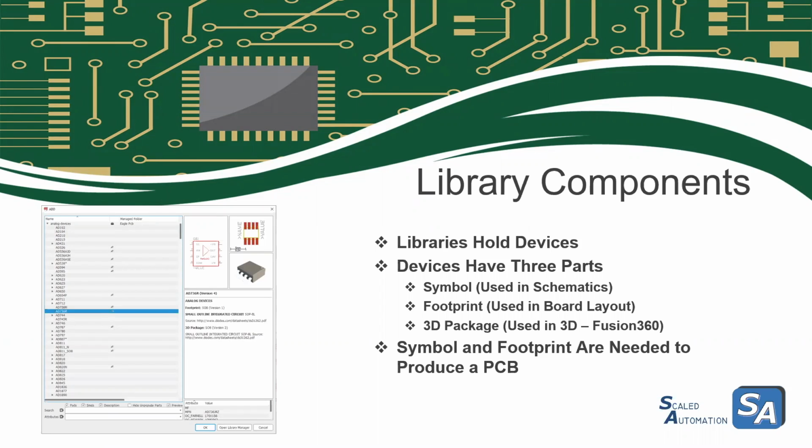Having said that, there's an exception to that, and it's an important one: things like mounting holes are also devices. They may not have traces to them, but they certainly have a footprint. They have a hole size, and they might have a piece of copper for isolation or a piece of copper connected to ground. So even a mounting hole is actually a device.